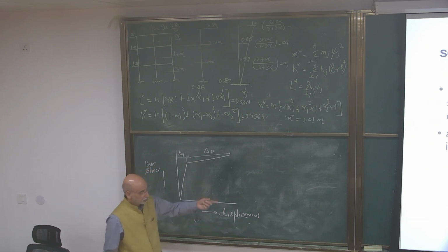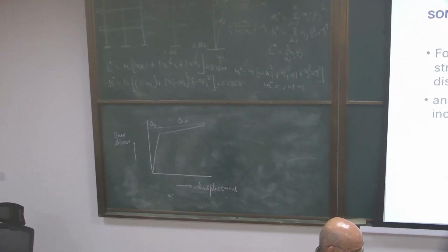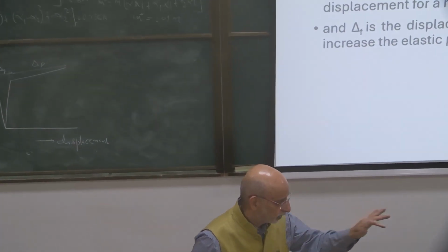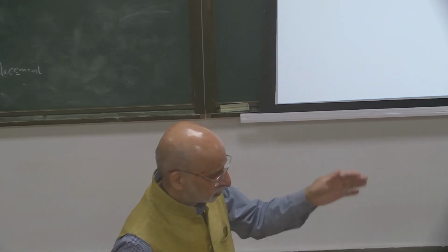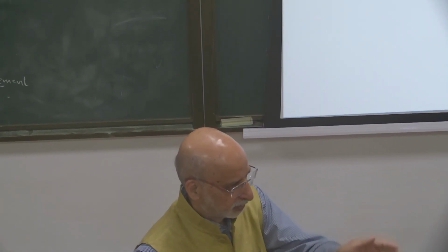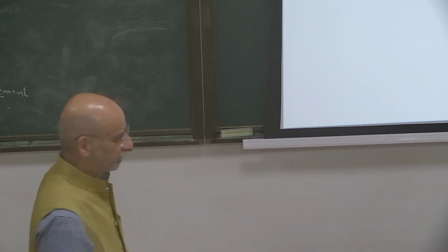That is the force-deformation curve I showed you this morning. There are two ways: one was the idealized one, and another was the realistic one, when you push a building slowly, how the deformation curve will come. So there is no damage, moderate damage, severe damage, collapse. It is a later extension of that one.